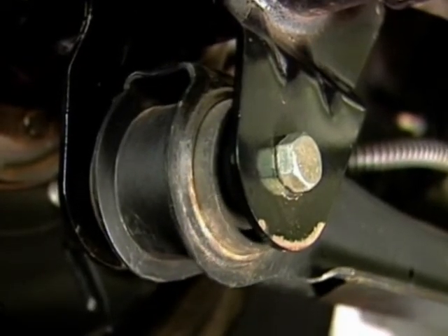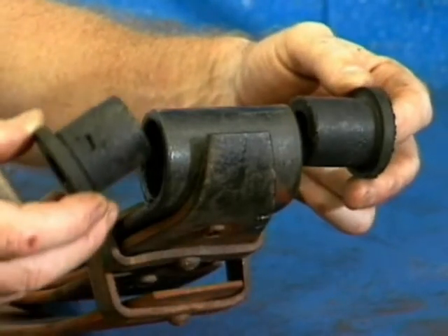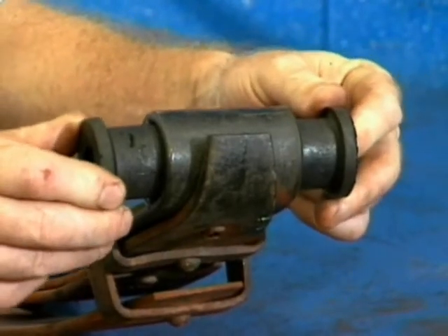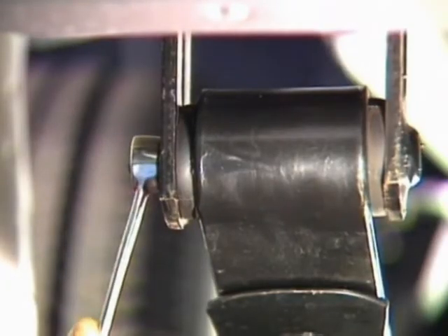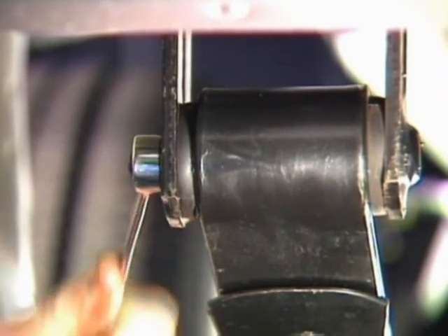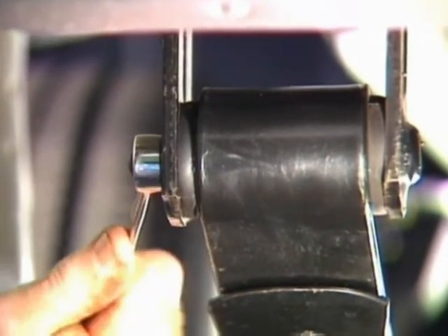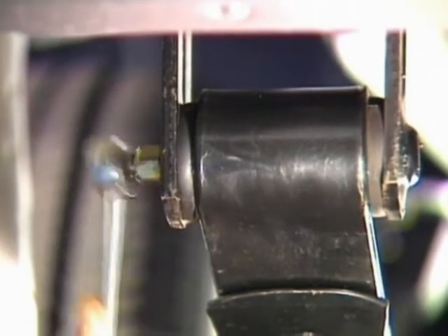Rubber requires no lubrication. Spring shackle bushings can be molded to form two halves, to fit into each side of the spring eye on the swinging shackle. With the spring loaded and the shackle plates tightened, the rubber is compressed in the eye and at the face of the plates. As the spring deflects, the rubber shears without tearing.